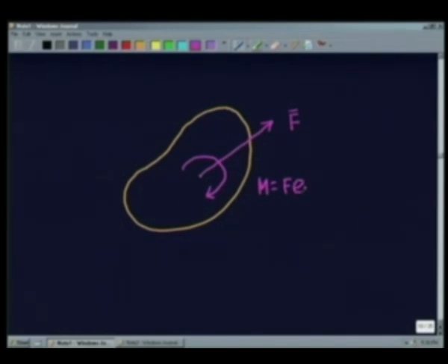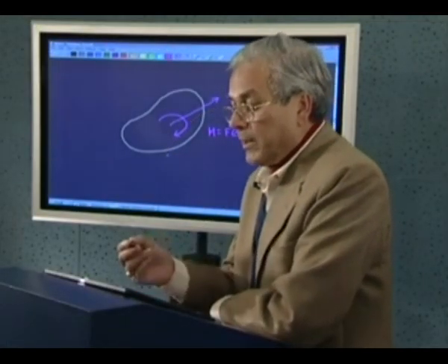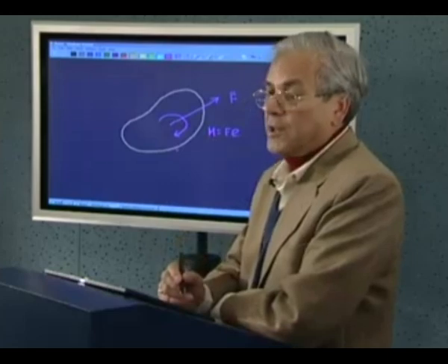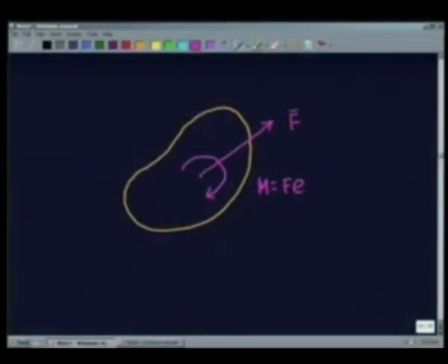Now you will notice that I have not put a moment vector here, because in plane motion all angular quantities, like angular velocity, angular displacement, moment, can be represented by algebraic quantities. Say we may consider that if it is in the clockwise direction they are positive, if they are in the anti-clockwise direction they are negative. So their summing up or subtraction is just like an algebraic quantity. Whereas force, its directions are different, and so it needs to be represented by a vector.